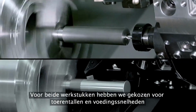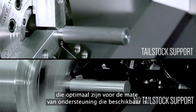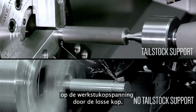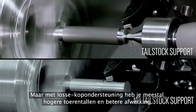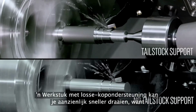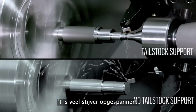Each of these parts are running with speeds and feeds optimized for the amount of support available. Machinists sometimes worry that they'll lose time waiting for the tailstock to clamp their part, but tailstock support usually allows higher speeds and better finishes. The tailstock supported part is able to run considerably faster since it is held in a much more rigid state.